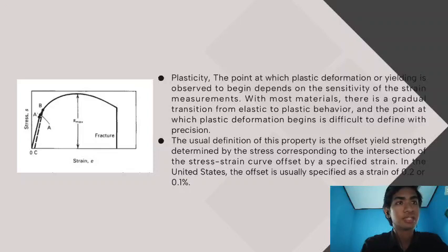The yield strength is necessary in estimating the force required in forming operations. Most structures must be designed so that a possible overload does not exceed the yield strength. When the stress exceeds a value corresponding to the yield strength, the specimen undergoes gross plastic deformation. If the load is subsequently reduced to zero, the specimen will remain permanently deformed.